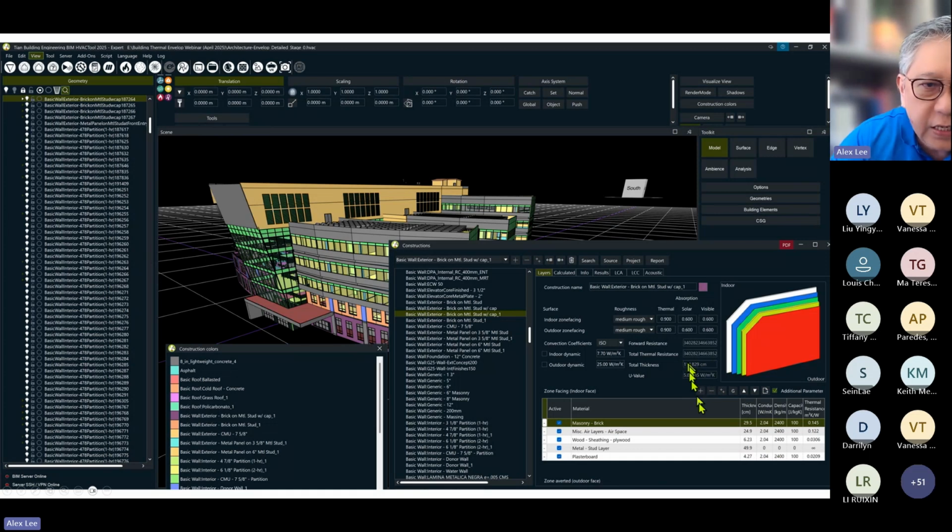So basically, you can get the correct material property, enter it into the system, and immediately you can get the U value of that piece of wall. This is exactly what our software can do. If all this material property or even the thickness is not available in the model, not to worry about it. As long as you know the layers, you can update and change the thickness and get the correct conductivity from a database. Bingo, you can get the U value of any wall you want.